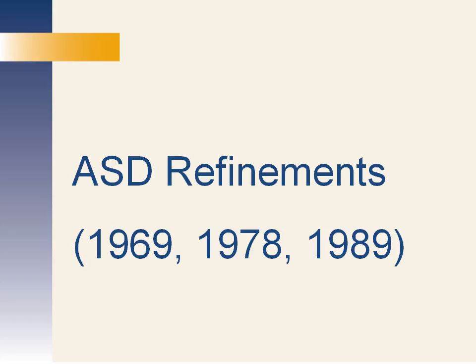Moving past 1963 into the era of ASD refinements, there were 3 more revisions of the AISC specification in its ASD form. These were made in 1969, 1978, and 1989. None of these revisions made any substantive changes to the column buckling equations or the interaction equations, but some other refinements were made, so let's look at them.